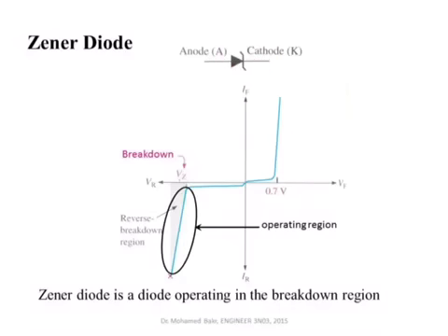And in that case, the current flowing from the cathode to the anode is almost constant, and it's determined by the external circuit components. And this is what makes this a great regulator, because you can keep the voltage delivered to the output or the load resistor fixed at, say, 9 volts or 5 volts with very little change for a large change in the current.